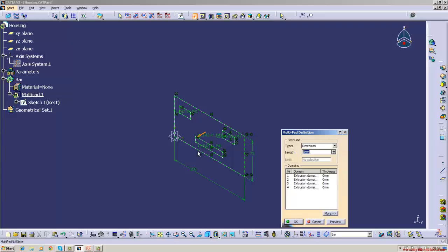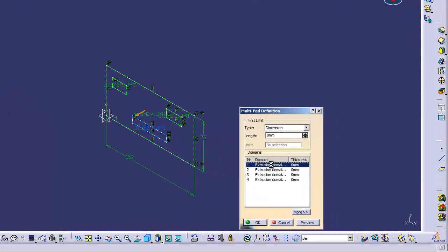There are 4 closed sketches, and they will be shown here. You want to assign the dimension, first to this one. Here you want to make it a projection, or extrude it to a pad. So you can say about 20 mm. Okay. Click here once again, it projected out. If you click this and zoom in, it's projected out.